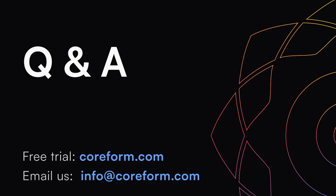Okay, an integration question. Since this is based on UEL mat, does that mean you're mapping the results to other simplified meshes for visualization? Yes, it does mean that. If you aren't aware, user elements are not supported by Abaqus CAE for visualization. If you do write them, I think you get out a node element at the centroid of the element, is how it's rendered. So the documentation points you to creating a kind of tertiary mesh that you map your results onto.